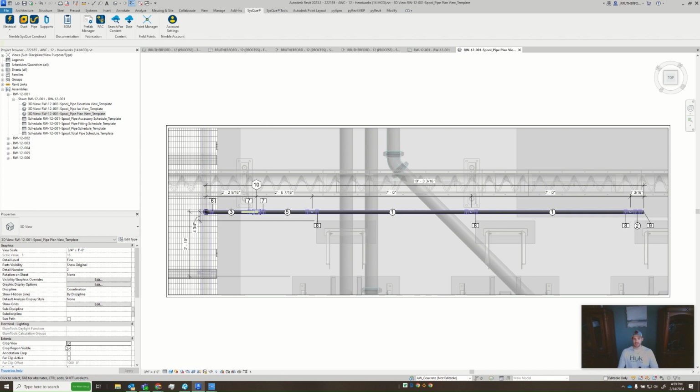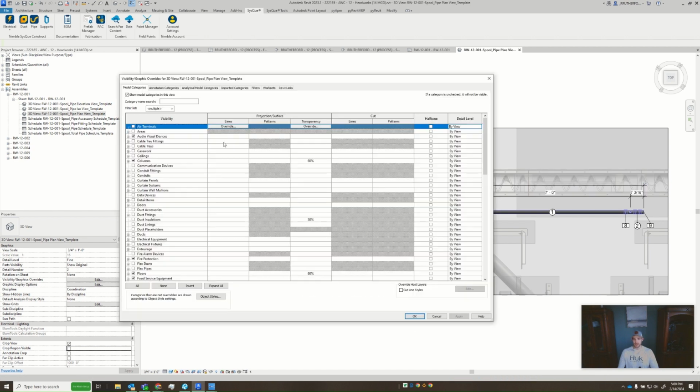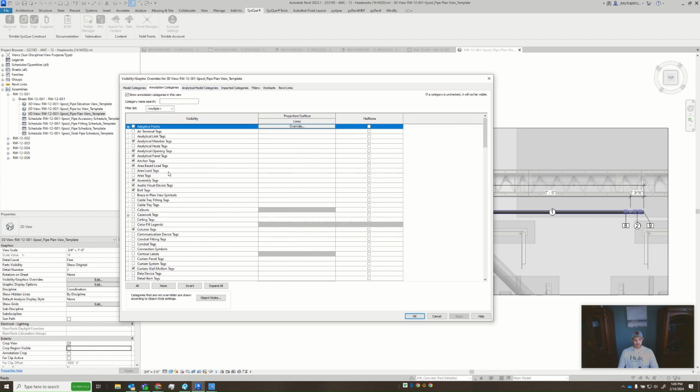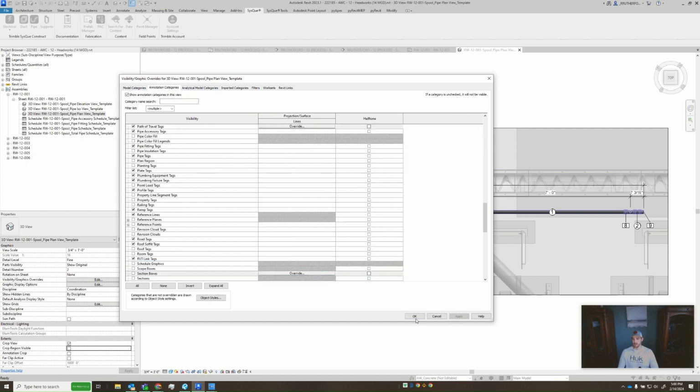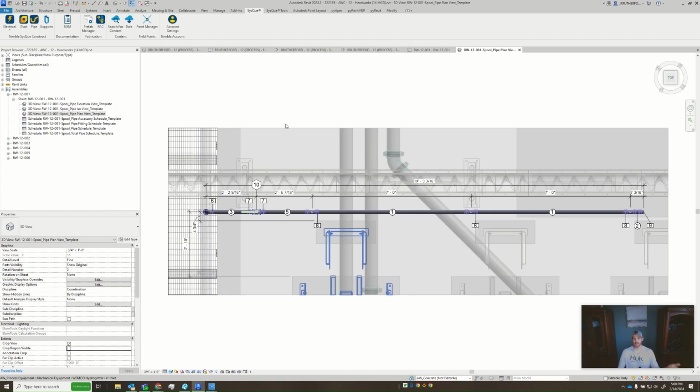So now I went ahead and turned the crop view back on, and we'll turn off the crop region. So now I'm left with this clean looking slate. VG, go to my sections, SE, turn it off. And again, that's a personal preference. When you export, it won't always have your section views on, depending how you set up your sheet, but that is my personal preference.